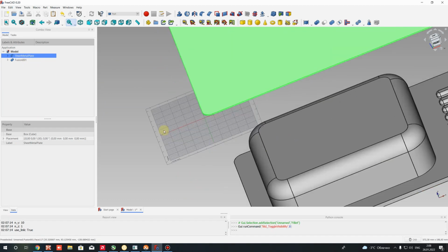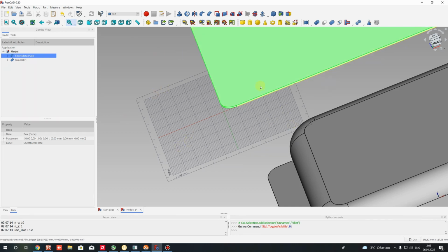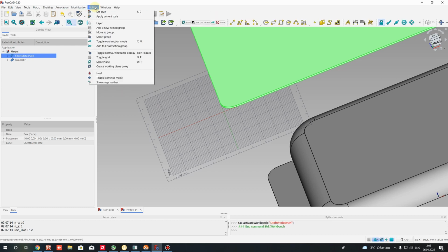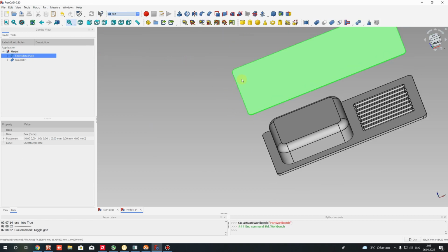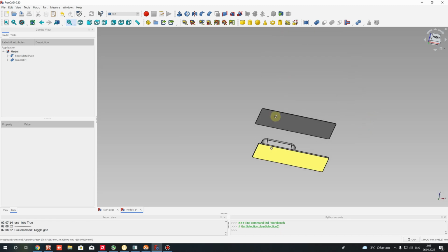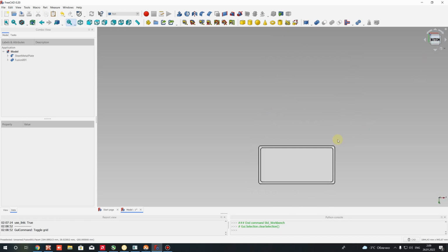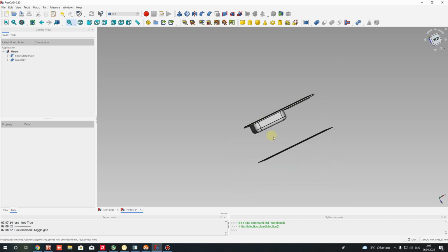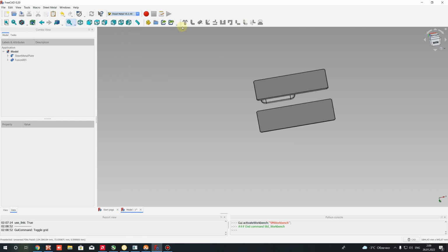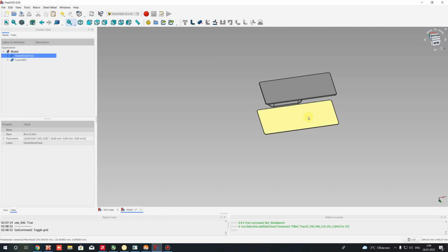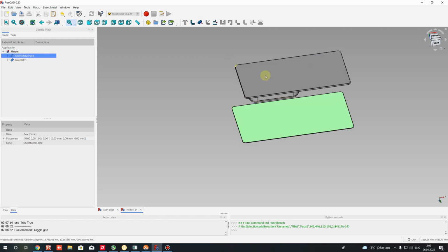And also in draft workbench, we activate this grid of mesh. Let's hide it in draft. Let's go to draft workbench, go to utilities, and let's hide it using this toggle grid. Hide it and go to part workbench again. Now you can see that we have this form for our plate. Let's go to sheet metal workbench and let's choose the face of sheet metal plate, this